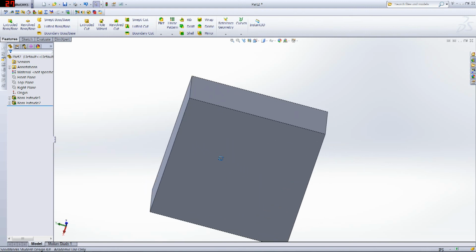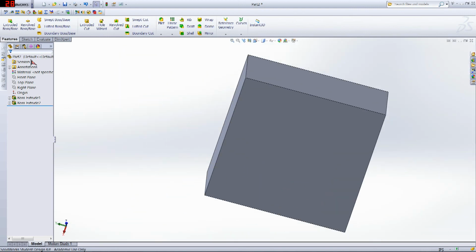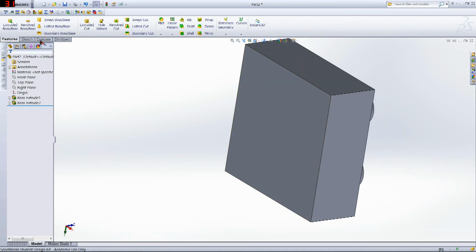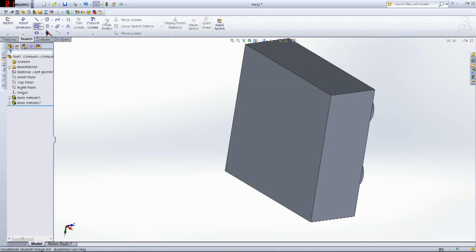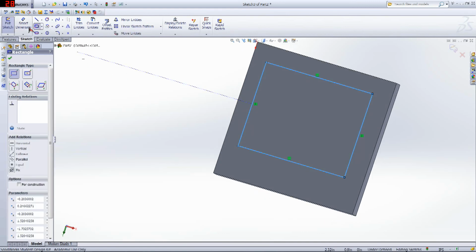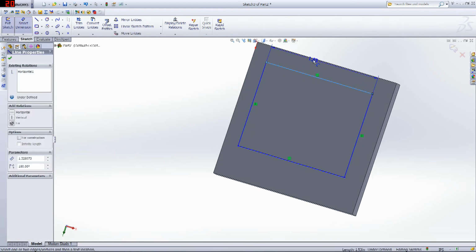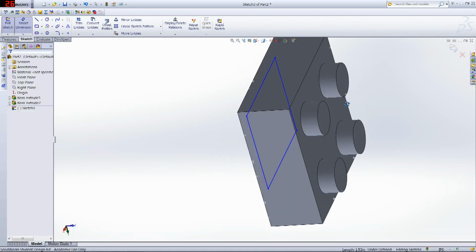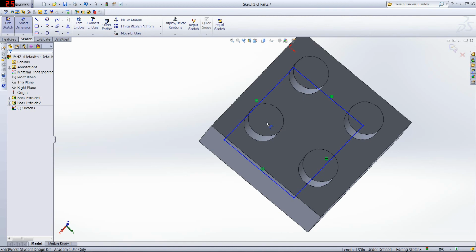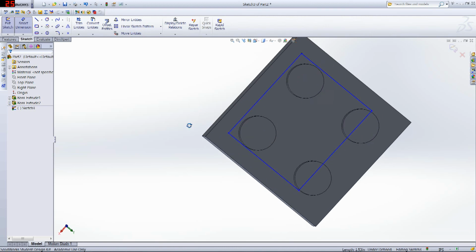Now for the back. For the back, you want somewhere for these pegs to go into. So you're going to start by drawing a box on the back. Like before, don't have to be so exact the first time. And for these, the diameter on these is 0.5, and they're 0.5. The center is 0.5 from this edge, so that leaves a 0.25 gap right there.